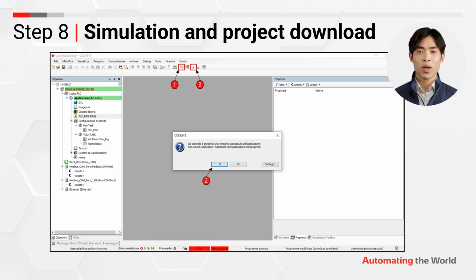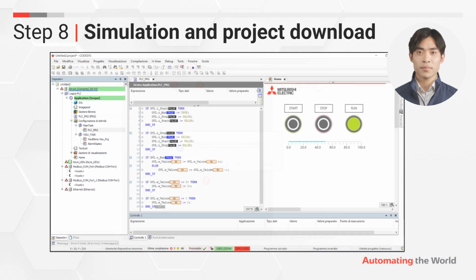As a first step, we'll log the project into the device. If there are any differences, the project is recompiled and downloaded to the device. Once the project has been downloaded, you need to put the device into play to start the logic. Only after downloading the project and putting it into play can you launch the home screen display and check that the PLC logic is working correctly.